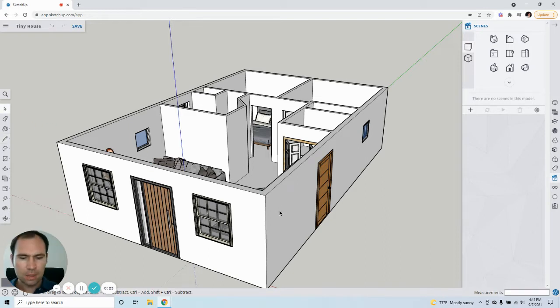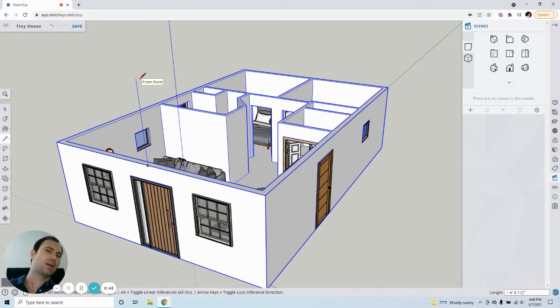Fortunately, our model again is grouped, so the roof is not going to stick to it. Now, we want our roof to be at the midpoint in the group. Typically we can get into the pitch of the roof, but typically an attic, from second floor ceiling height to peak of attic, is maybe 6 feet, maybe more, maybe less. We're going to go 6 feet. Depending on what kind of pitch, how sharp you want your roof to be, we can decide from there.